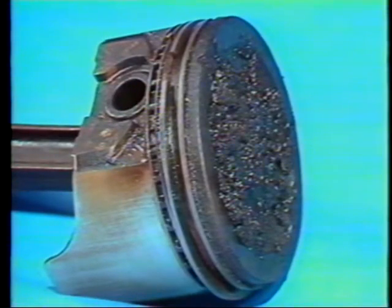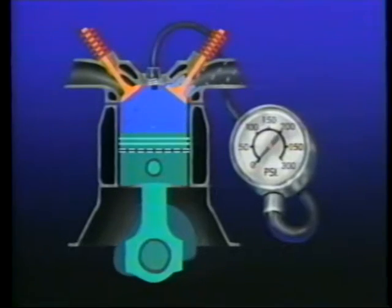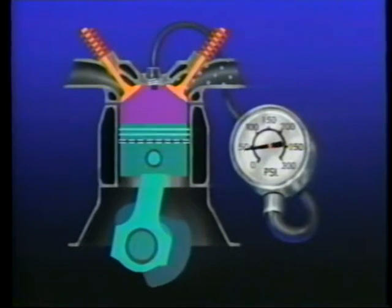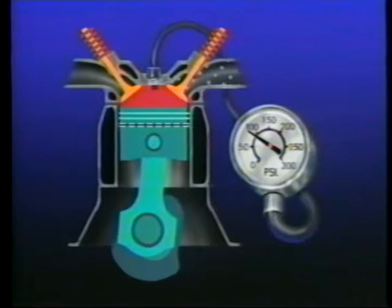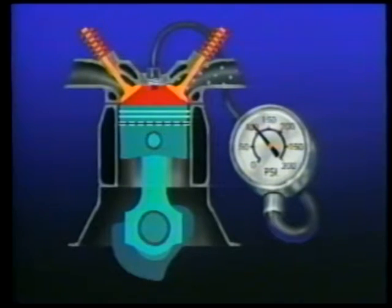Carbon buildup on the pistons would actually increase compression pressure because the carbon displaces a portion of the combustion chamber volume. And when the air-fuel charge is compressed during the compression stroke, it's compressed into a smaller pocket. When a gas is compressed into a smaller volume, the pressure exerted by the gas increases.